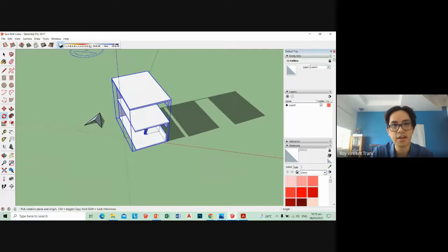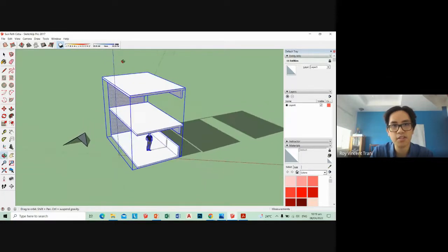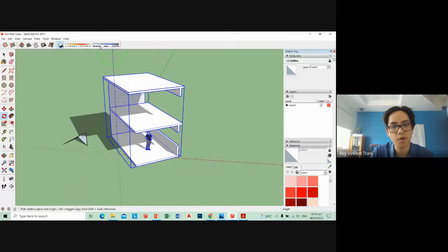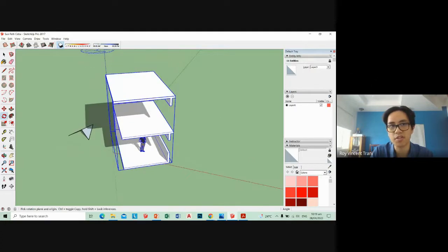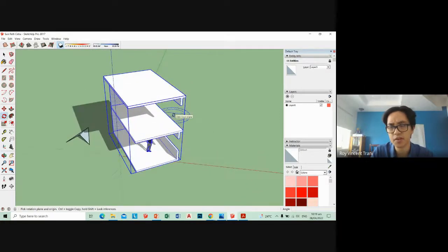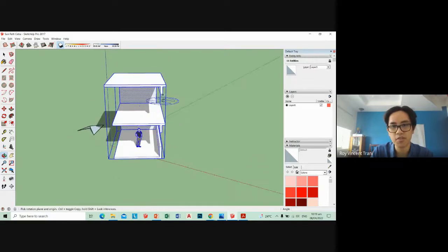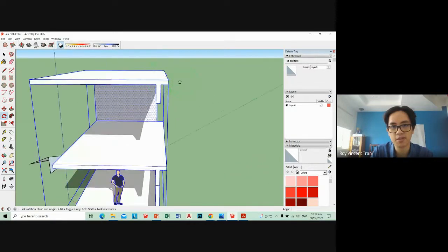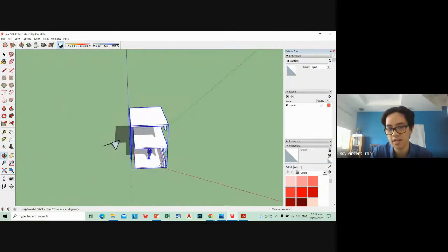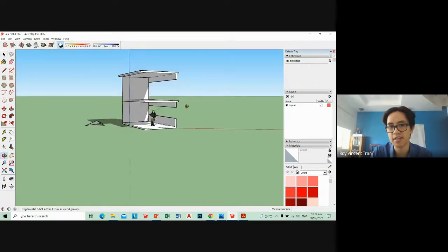And then let's just check out the December situation. In December, the afternoon sun is even at a lower angle, so there's more exposure on the western side. In the morning, the sun comes in even more. In December, the angle of elevation of the sun is lower, so there's more exposure on your bus terminal. So this is where the 45-degree roof eaves doesn't really function. It's good for rain, but not so much for sun. So that's something that you need to figure out.